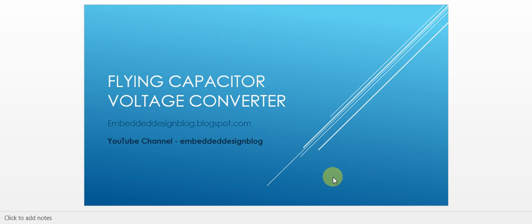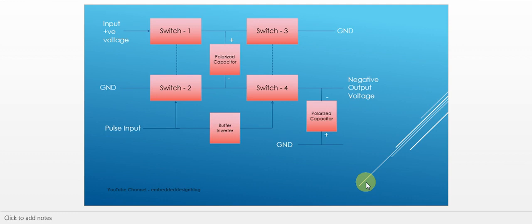Now, one thing we have to see here is that nowadays most embedded applications use ICs, where you don't need the discrete circuitry. Even for this specific circuitry, there are ICs available in the market which can generate positive to negative. Most embedded designers use these ICs because of their space constraints, rather than designing a discrete solution and having the trouble of debugging and bringing up that specific circuit.